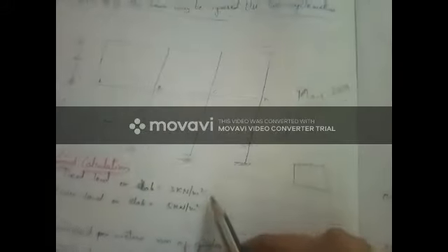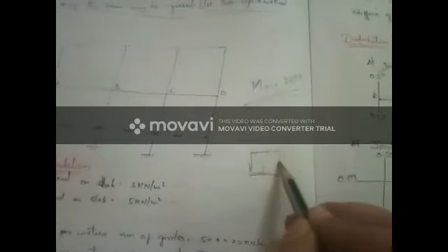So as this is the slab, the load acting on the slab is, dead load is 3 kilonewtons, live load is 5 kilonewtons, but here the load will be transferred to beams and columns as well. So we will not go for any complications, directly we will take that 3 kilonewtons of dead load is transferred to girders.